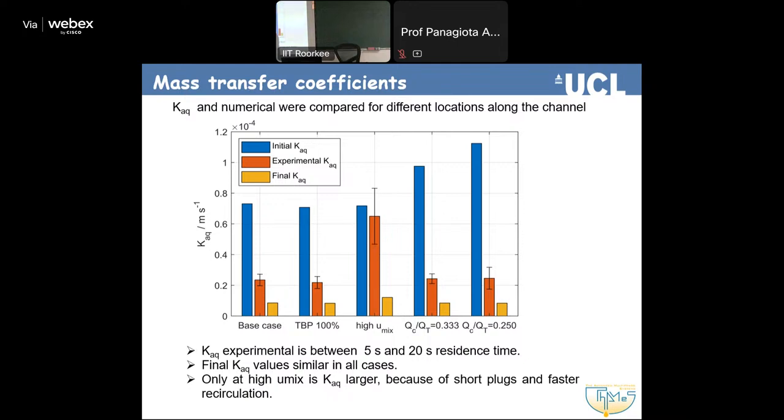So this is now the mass transfer coefficient without the area, just due to the mixing that happens. And because we also used our modeling, we had the mass transfer coefficient we got very close to the inlet, and the mass transfer coefficient we got at the end. And the one we get from the experiment, which combines both these effects, luckily enough, was actually in between these two extremes. Because this one we measure contains that and some length. Okay, and we see that repeated.